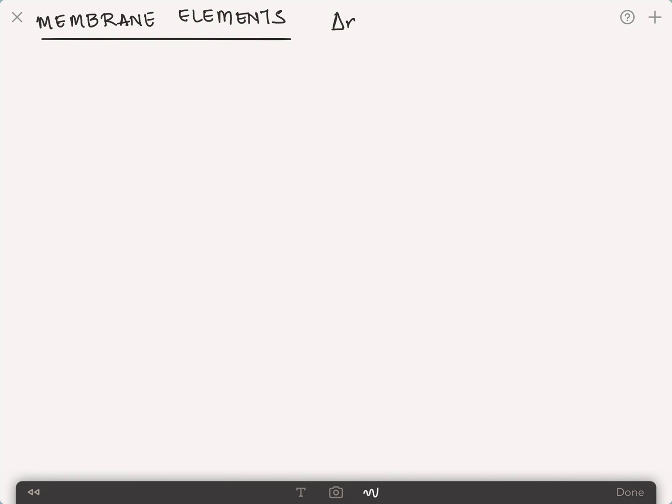In this video, we will discuss triangular membrane elements. We will start in this video particularly with the displacement behavior, and in subsequent videos get ahead with setting up the stiffness matrix and the load vector, followed by the transformation matrix for the stiffness matrix of this element.